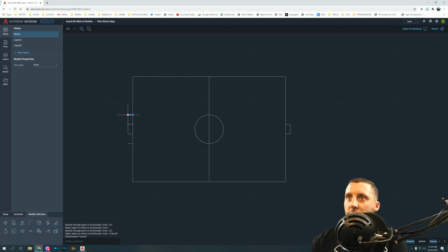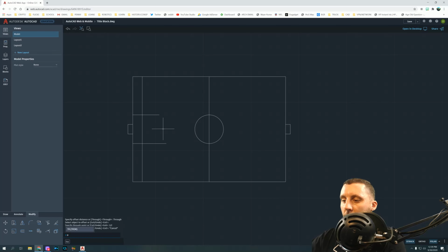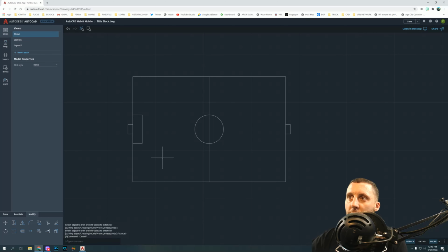Well, what I'm going to do is I'm just going to grab the left blue mark and I'm just going to go like this, and I'll trim off the rest later. It doesn't matter how far you go. Alright, we'll trim the rest later. Alright, offset. Click the line first. Go to the right, 1/2 inch. Enter. So now I can either trim, or I could use a fillet radius 0 and do the corners like we normally do. That's fine too.